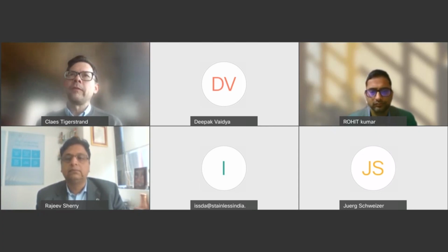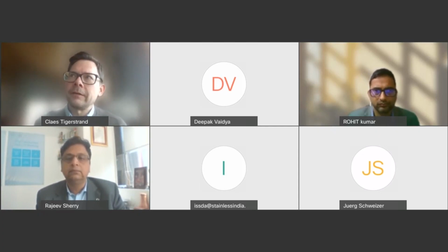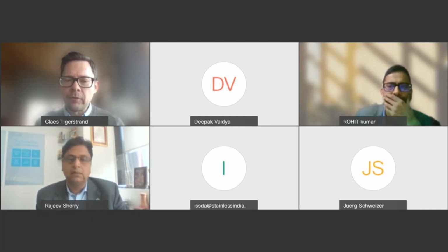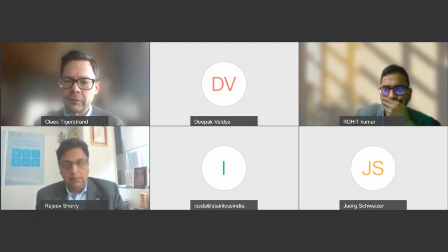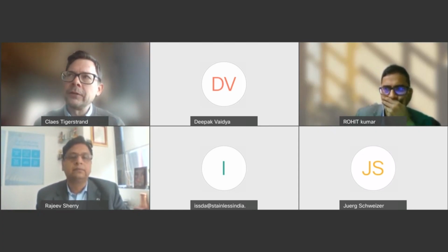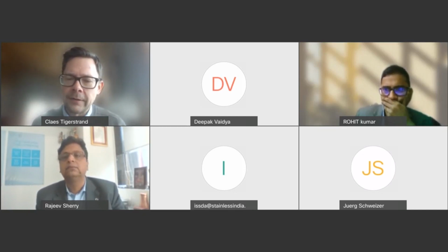Yeah, that is a very good question, and there are a few options there. Normally, in a location like that, you will not do a pickling operation as a post-weld treatment, because from the environmental point of view, it is tricky to do that. What you can do then is mechanical cleaning with brushing of the welds, using a slightly rougher brush first and then a finer brush.